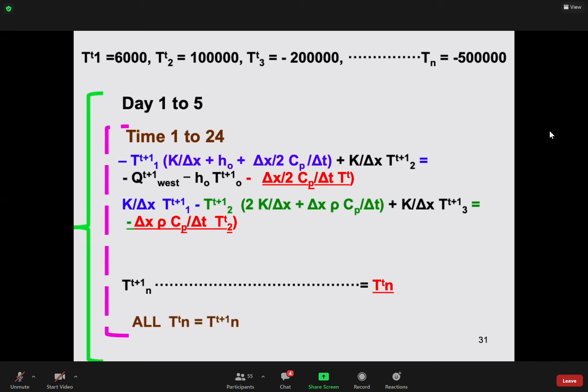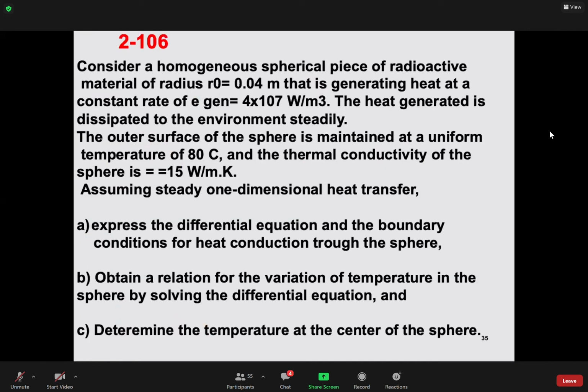Therefore, the same thing that you did for project number 1, it follows the same format, but now we are also looking to see how the mass of the wall will affect the temperature distribution in the wall. You will see it in your result. There will be a delay. For example, in the morning, you have a lot of radiation on the east wall, okay? But the temperature will not pass through the wall immediately. Probably it takes 3 or 4 hours to reach its maximum and show the temperature variation, okay? Therefore, you will see your graph shift a little bit, and we call that time lag. Any question?